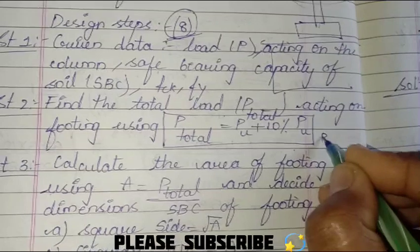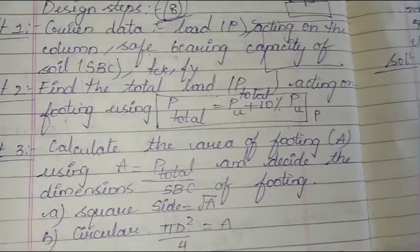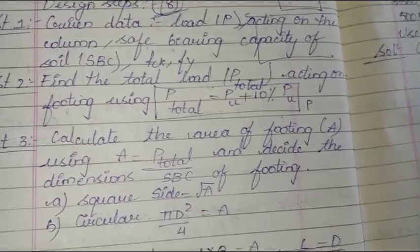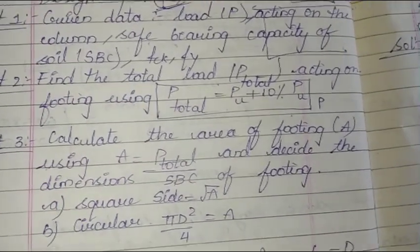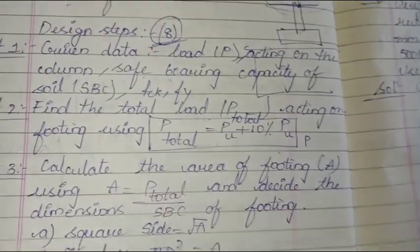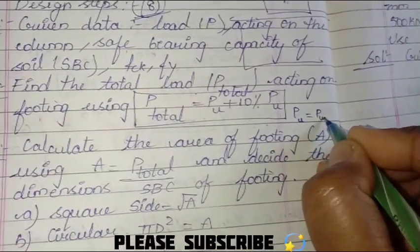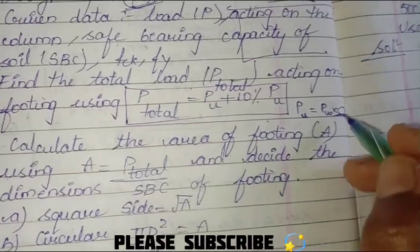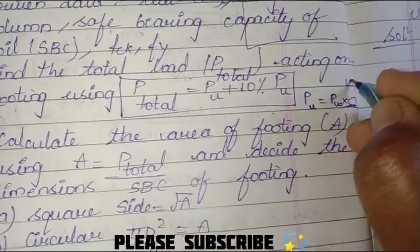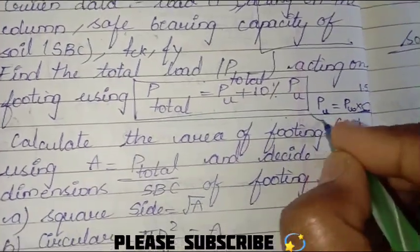As I have explained in the video regarding the design philosophies of RCC members, I explained the ultimate load concept. I will also provide the link of that video, or you can check it out on the channel, guys: the design philosophies in the design of RCC members. In that I clearly explained that Pu is nothing but Pw multiplied by some factor, the load factor. The load factor is generally taken as 1.5.